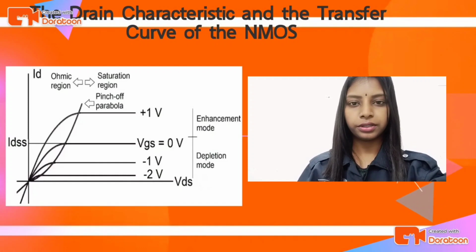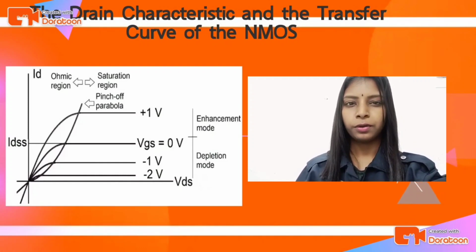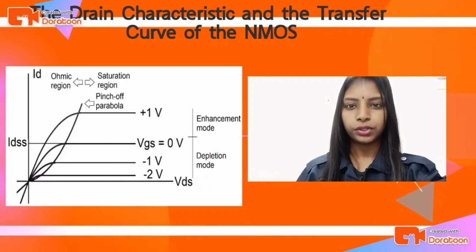Extending the drain characteristic to high values of VDS will encounter a breakdown region where the drain current rises quickly. The breakdown mechanism is the avalanche effect in the space charge region at the drain end of the channel, when the voltage drop across the region is substantial.